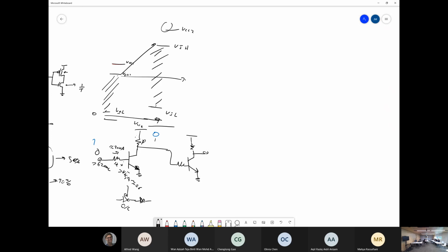And I guess transmission lines, there's a lot of maths going on with those. To do transmission lines properly, if you want to do it analytically, you need to deal with the telegrapher's equations, right? You need to write, I believe, a Helmholtz-type equation from your infinitesimally small transmission line model. If you have a transmission line and you boil it down, you get something that looks like this, and some shunt conductance in there.